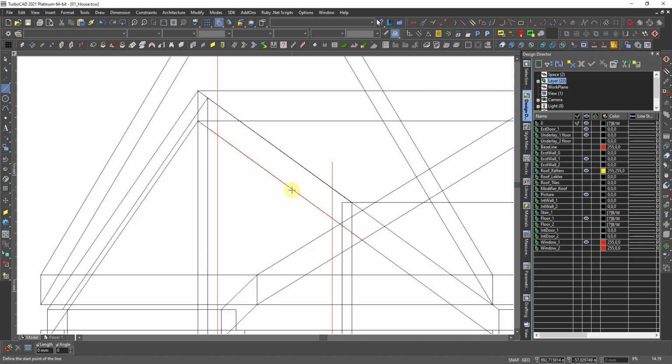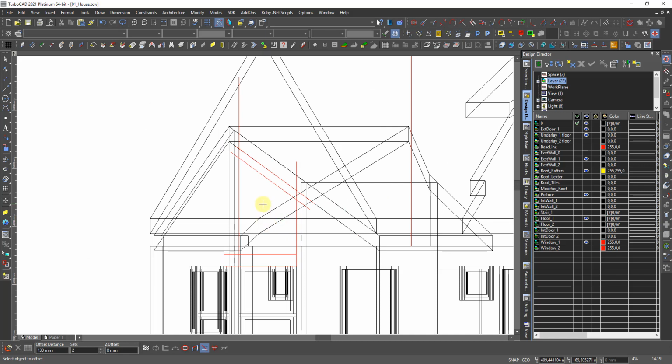I think this ceiling is coming down here, and there should be a little bit of place for the moldings also. So I basically use 130 millimeter down there, old habit. So offset 130, enter, and take that line and down here. This is the maximum.